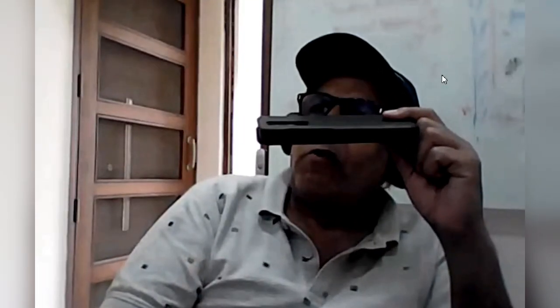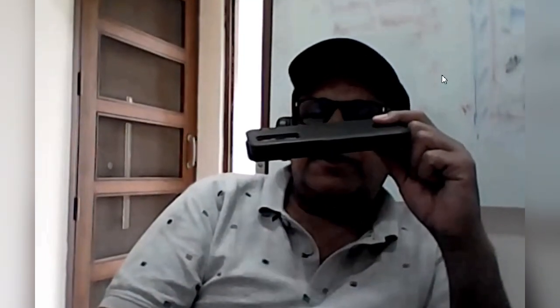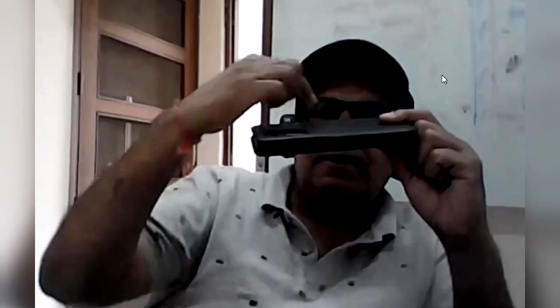When the ship pitches it is about an athwartship axis, right? Or whenever she trims, it happens about an athwartship axis. Am I right? Right, sir. It acts like a fulcrum, sir. Yeah, the center of flotation acts as the fulcrum of the ship, but the axis, when the trim changes, it changes about this axis which is passing through the center of flotation. Yes or no? Yes, sir. So longitudinal stability, which is the change in trim or pitch, is about an athwartship axis.